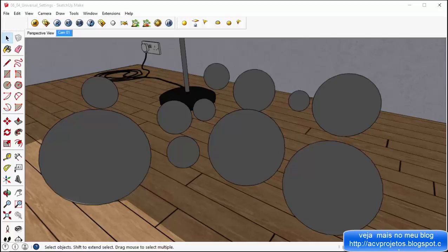Universal settings work because the high primary subdiv value that it uses essentially causes most, if not all, of the sampling in a scene to be performed by the primary rays, rather than making use of the secondary ray subdivs that are available on many materials and lights, etc. These primary rays will use as many samples per pixel as required in order to achieve the specified noise threshold. In many ways this is similar to a progressive path tracing approach, only here we are working on a per bucket basis.